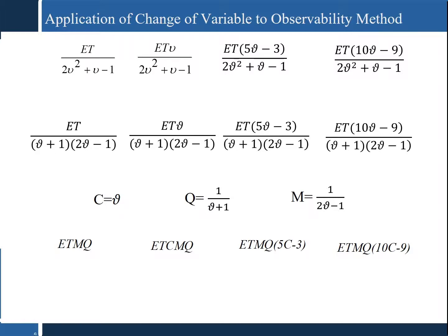And on the other hand, when we transfer the unknowns from the stiffness matrix to the vector of delta, they are getting multiplied by our deflection, which leads to a nonlinear equation. To solve this problem, a change of variable is proposed. This change simplifies the mathematical resolution of the system and enables the application of the observability technique as the new unknown parameters appear uniquely in the matrix.